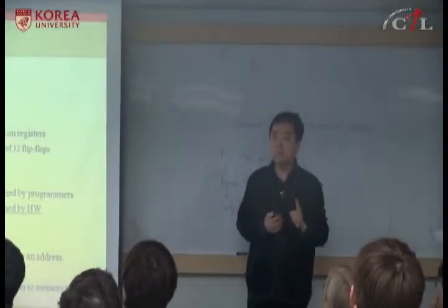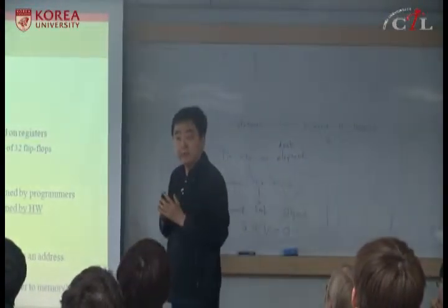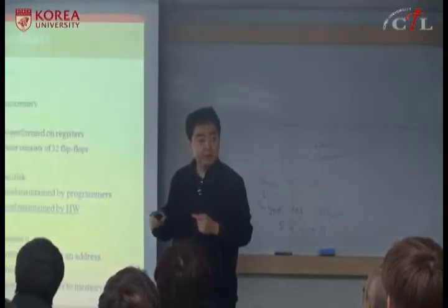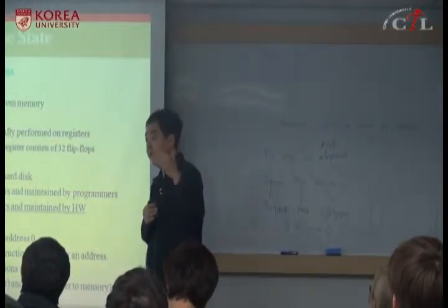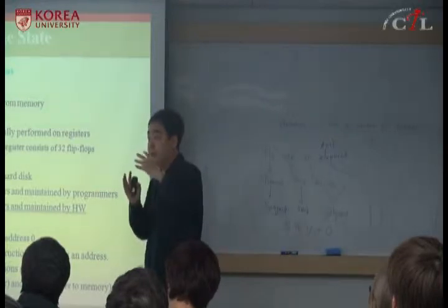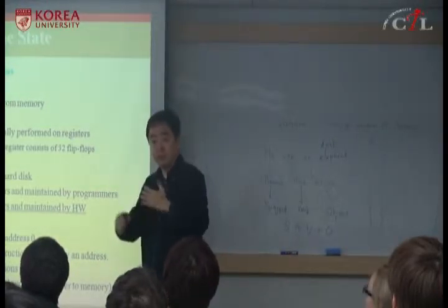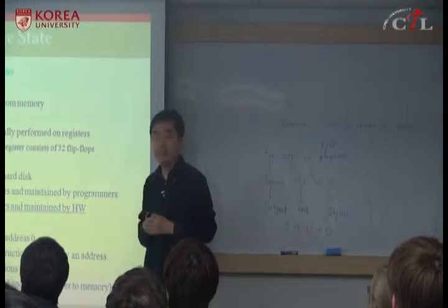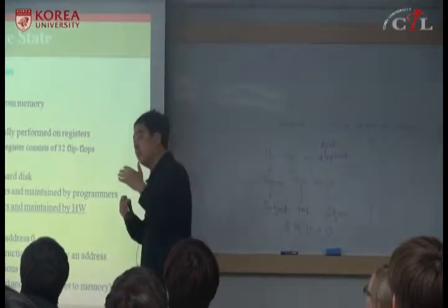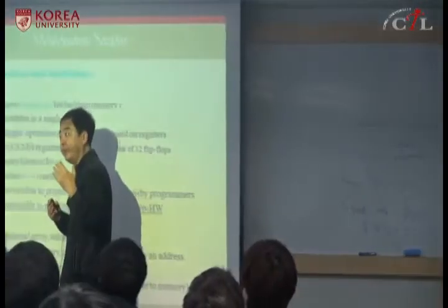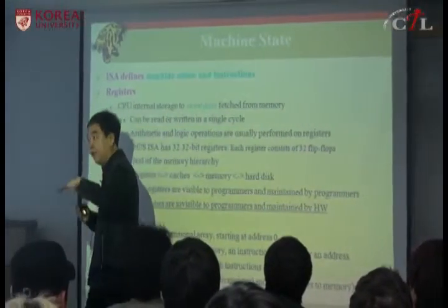One flip-flop is a static RAM cell, right? Because it has a loop. Loop means as long as power and ground signals are supplied, you can retain your state, right? Because of the loop, you keep writing the value. That's a static RAM cell. Dynamic means even though the power is supplied, you lose your state because of leakage current.